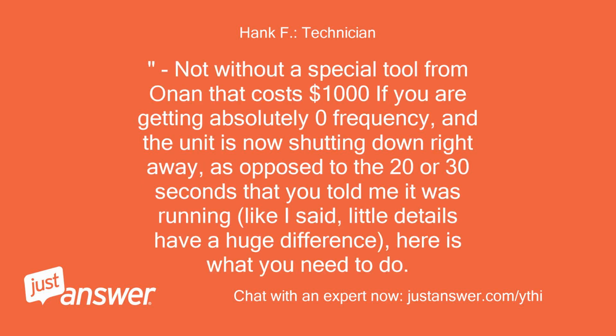Not without a special tool from Onan that costs $1,000 if you are getting absolutely 0 frequency, and the unit is now shutting down right away, as opposed to the 20 or 30 seconds that you told me it was running. Like I said, little details have a huge difference. Here is what you need to do.